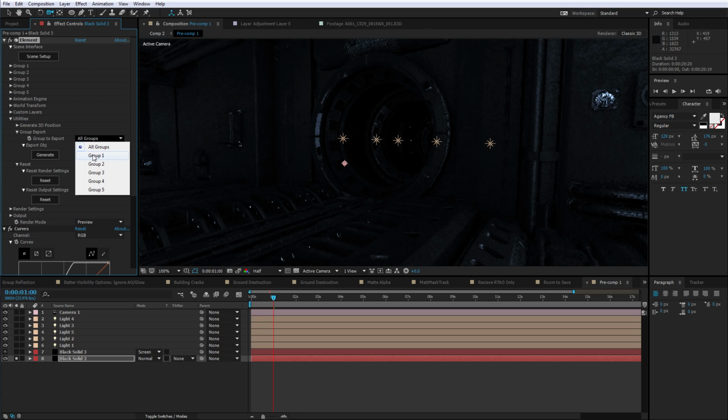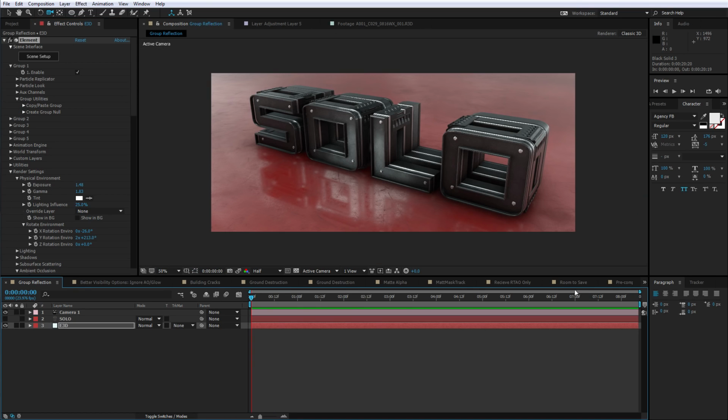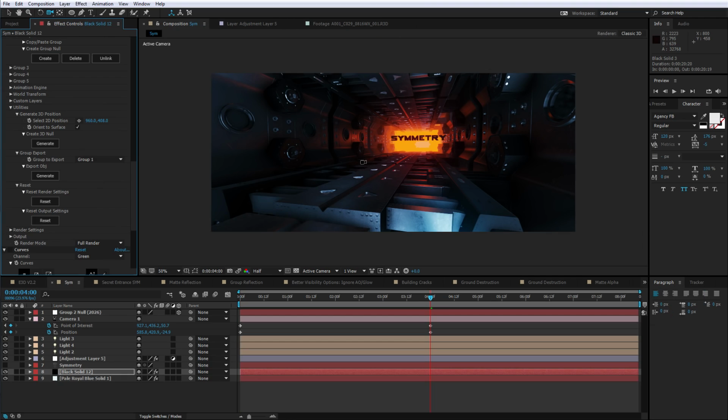For an individual group, and this is great, let's say you create a cool logo or something that you want to bring into another 3D program, or you want to save it and import it back inside of Element 3D. You could export the entire group as a single object with an E3D file. Just keep in mind that it could take a very long time and you might create OBJs that are way too large. Just be careful because it could create a huge file with all the different geometry that's been repeated.